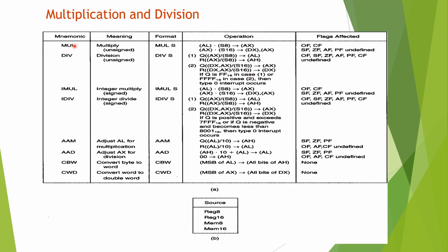On executing multiply and divide, most of the flags get affected. Overflow and carry flags get affected. Sign flag, zero flag, auxiliary and parity flags are undefined.